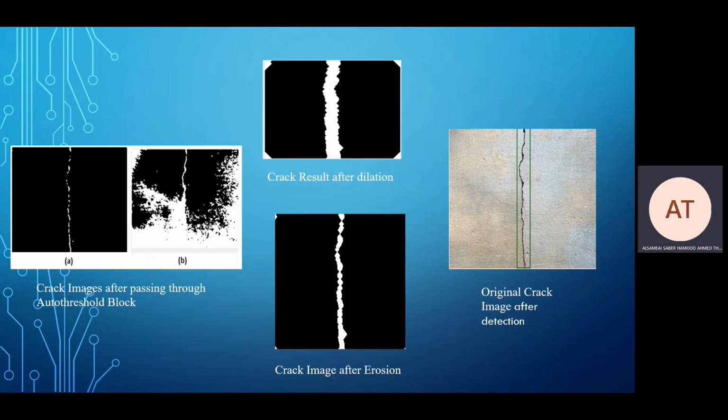The crack image after the dilation process. Here the dilation with the diamond structural shape and radius 12 was applied. Comparing the dilated image to the previous image, the holes are completely filled up, and the crack is now considered as one line. However, the shape has been deformed and has become thicker. Thus, some further morphological operation was required.